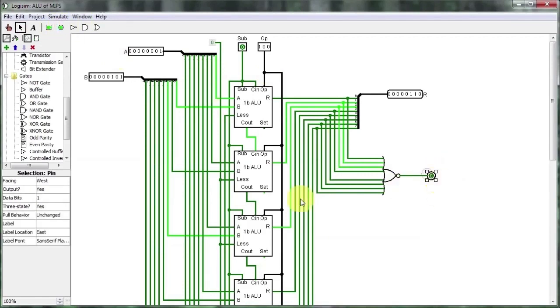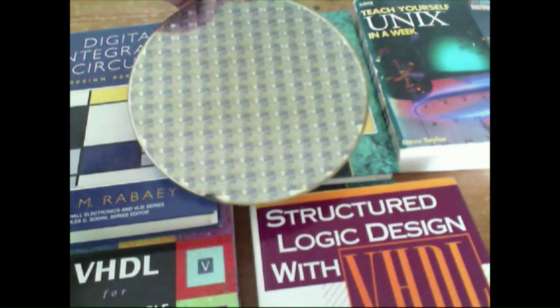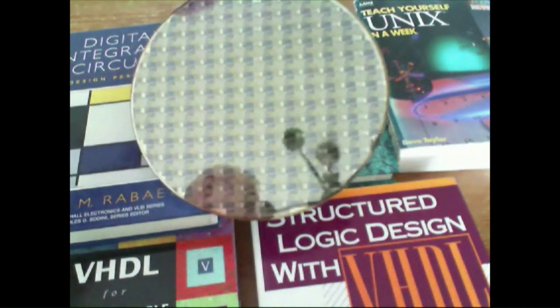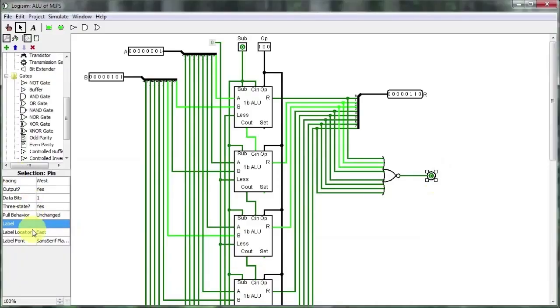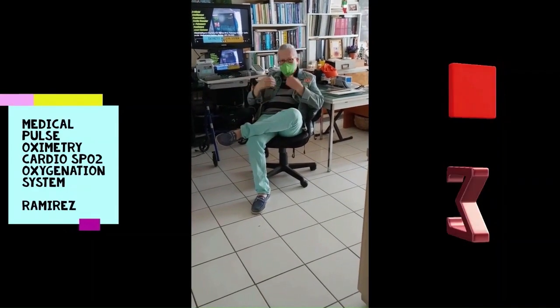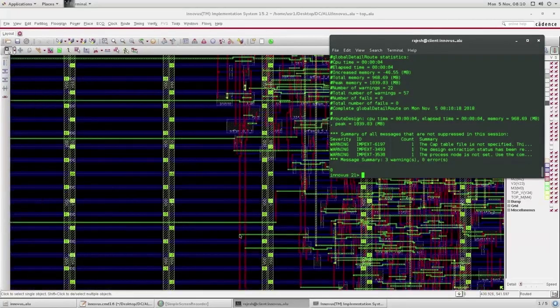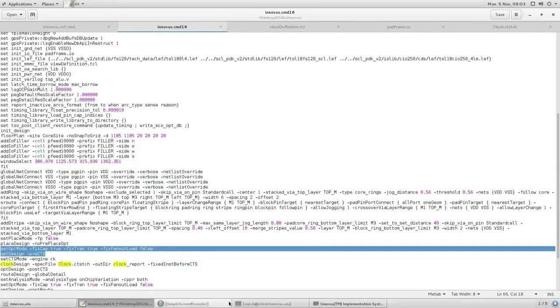Once the logic has stabilized, more emphasis is placed on achieving a high quality and legal placement. Some placement tools do ignore at least some aspects of legality during the optimization phase. Both clock optimization and power optimization. This overlap can simply be removed through a brute force technique, or overlap removal can be performed with some of the placement optimization.